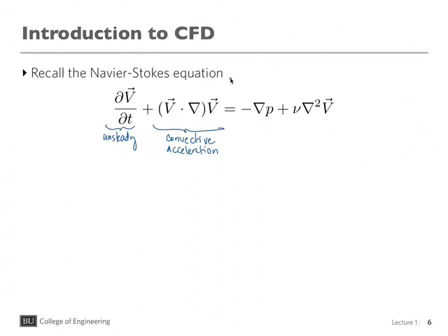And the other one represents how the velocity changes because a particle of fluid moves from one place to another place. That's why we call it convective. As a particle of fluid, a small little drop of fluid, moves from one place to another place, it has the effect of moving within this vector field, and therefore its velocity changes. That's this contribution over here.